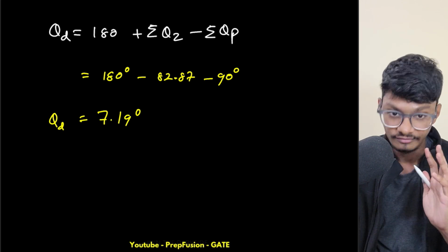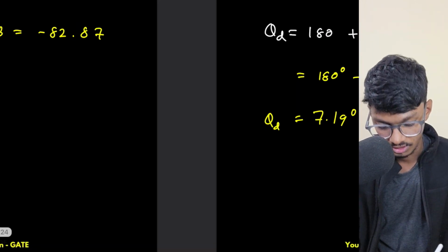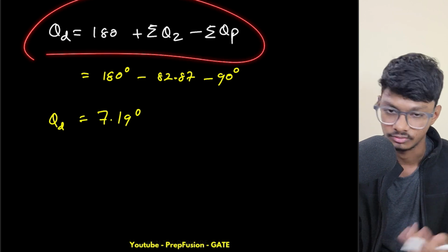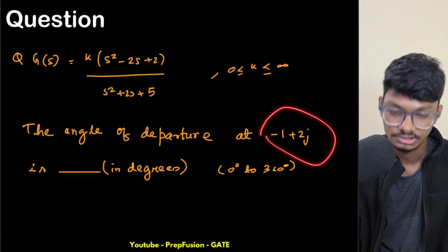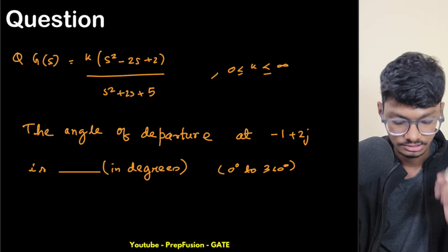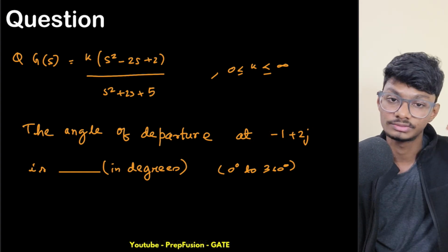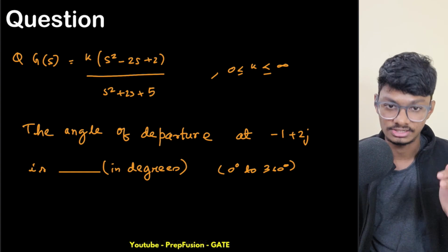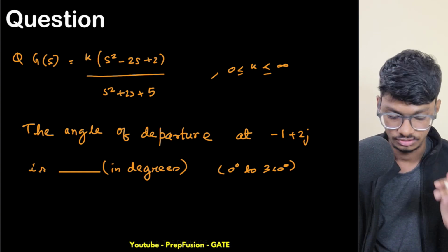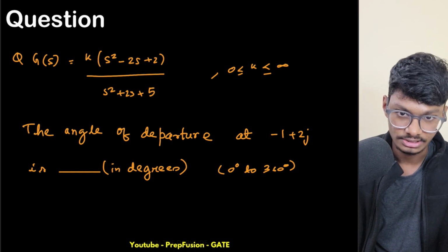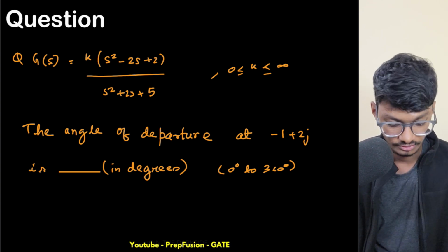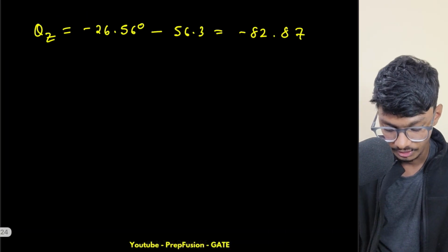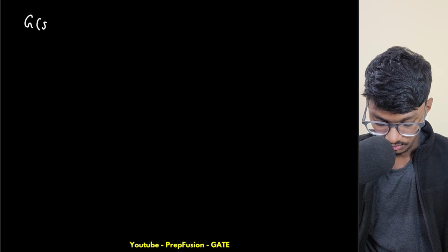This is where the formula comes from. We know that this point is lying on my root locus. If this point is lying on my root locus, then it has to satisfy my angle and magnitude condition. So if I use the angle condition, from there you will understand. If I put this in the OLTF, what is my G of s?